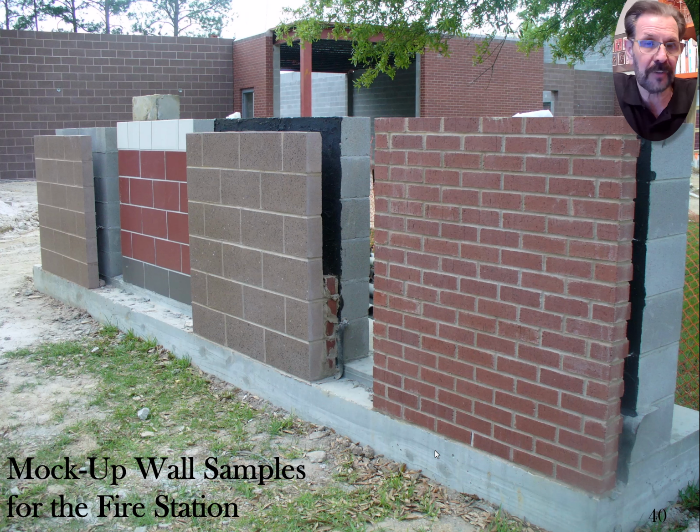The third section over there, it's set back because they've got the ceramic tile blocks that we were looking at. You see how they're laying them. They get installed at the same time they're installing the block, they're also installing the tile because it's already fused to the blocks, and so it's a nice idea. And my point is just that this is a much better example of a mock-up for you to understand.